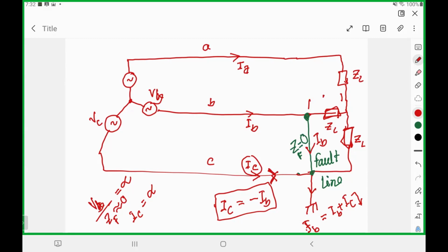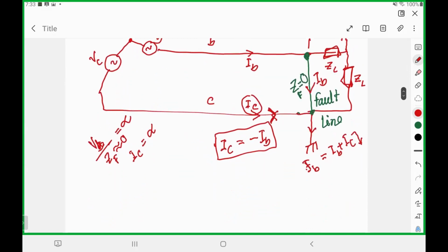So with these 2 points shorted, I can expect 0 voltage across these two phases, almost 0, negligible voltage across this phase. With a fault, the current has gone high, so the voltage must have dropped away across those two phases. That will be very low, right? Yeah, so that's what we are expecting from this one.